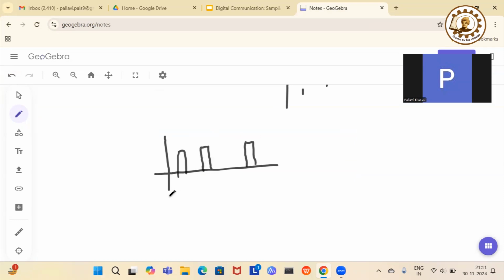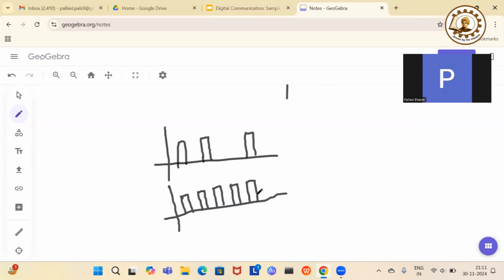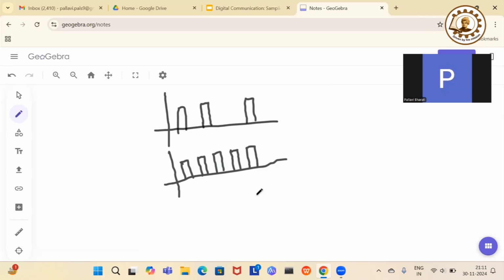These are your PPM pulses. Now there will be a reference pulse generator which will be at fixed points. So say it is at this point, then this point, then this point. Now these are at fixed intervals. Fine. So what is going to happen is, whenever this one is at the reset pin, this is the PPM pulse, this is the reset, and this one is the set. So the output will be this way.